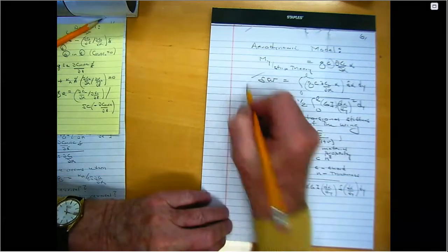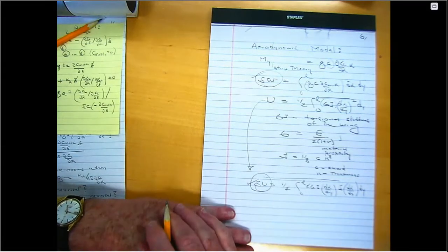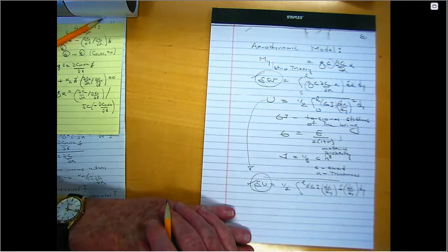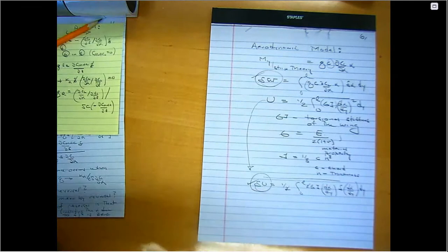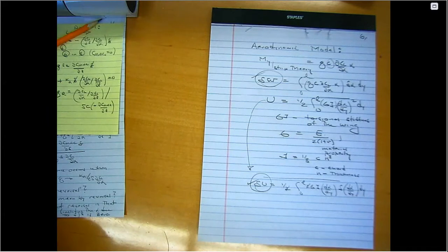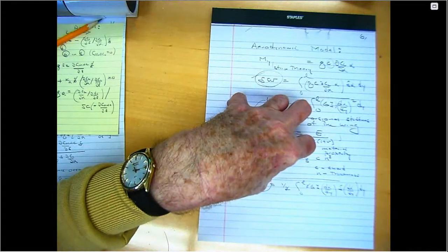And so now I have an expression for del W, and I have an expression for del U, and I'm about halfway there. I have two more things to do. First of all, this del alpha, this virtual change, is anything I want it to be. Therefore, the equation of equilibrium, which I'm about to find, has to be valid whatever del alpha.